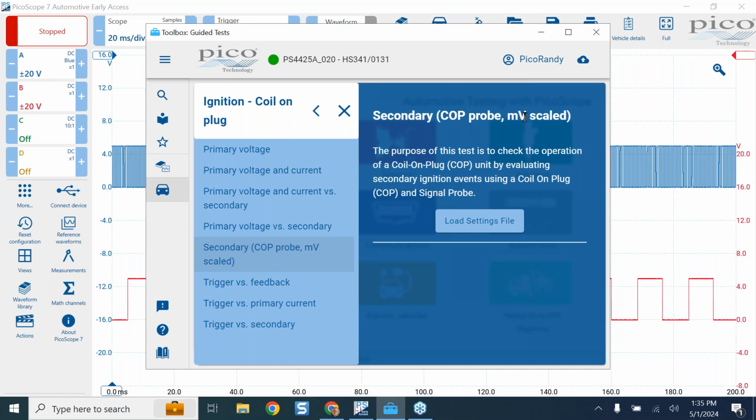So you get a picture, and the picture looks really accurate compared to what we're used to, but the scaling is in millivolts because the probe, and almost all these wands, all produce an input in the front end of the scope in millivolts. They don't put kilovolts through an attenuator into that. They use millivolts. We went to that across the board, and there's no more kV. There's no more guesstimation from us. It's millivolts, and that's what you're going to read.